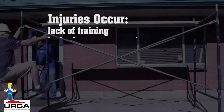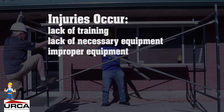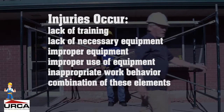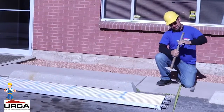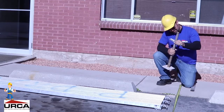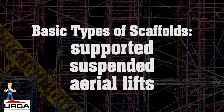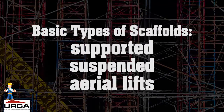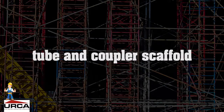Injuries occur because of a lack of training, lack of necessary equipment, improper use of equipment, inappropriate work behaviors, or a combination of these elements. To prevent accidents and ensure safety, the roofing industry needs to train its workers in proper erection, operation, and dismantling of scaffolds. Though there are basic types of scaffolds, supported, suspended, and aerial lifts, this presentation will only cover the most common supported scaffold used in the roofing industry, the tube and coupler scaffold.